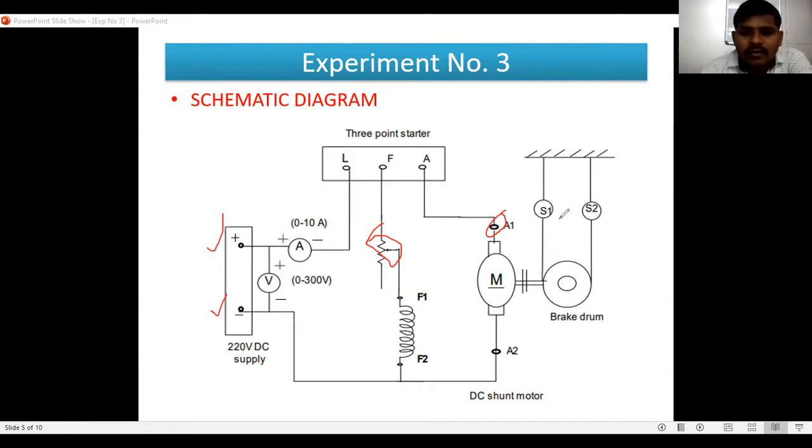See, here there are two meters to measure the load put, in kg. S1 and S2 show how much load is put on the motor, and we take the difference between them. If we want to convert this force into Newton, we multiply by 9.81, and it can be converted into torque.